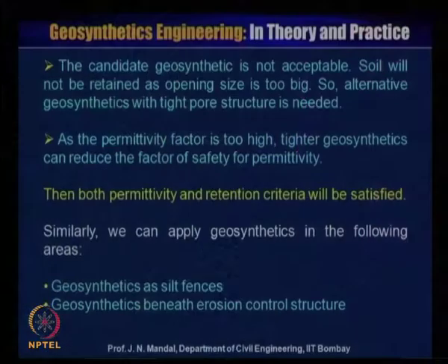The candidate geosynthetic is not acceptable; soil will not be retained as the opening size is too big. So, an alternative geosynthetic with a tight pore structure is needed. As the permittivity factor of safety is too high, a tighter geosynthetic can reduce the factor of safety for permittivity. Then both permittivity and retention criteria will be satisfied.